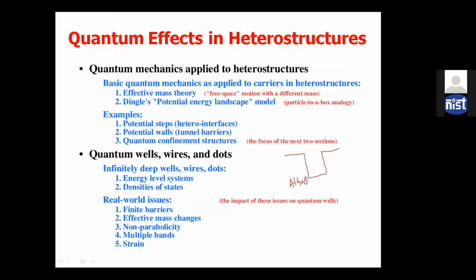So here, as per the effective mass theory, the effective mass is different inside the channel, inside this well, as compared to the outside. And when we go for this boundary condition, if you take an infinite well, that means the energy is confined, the electron is confined only within the boundary.